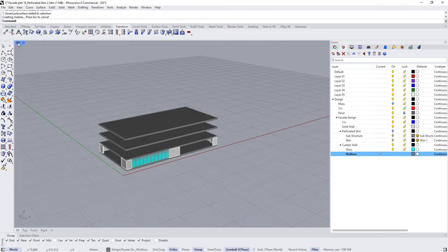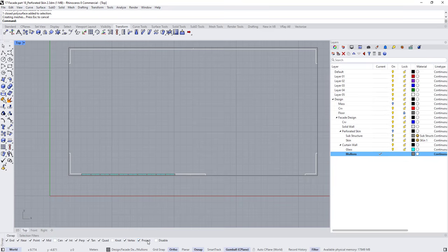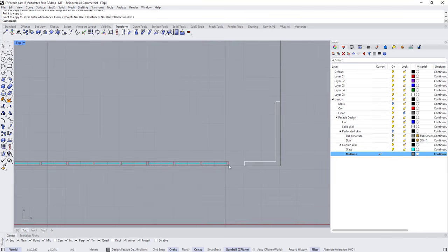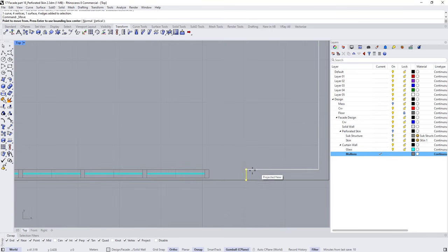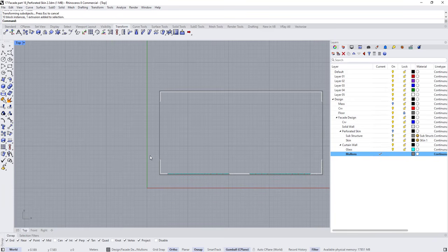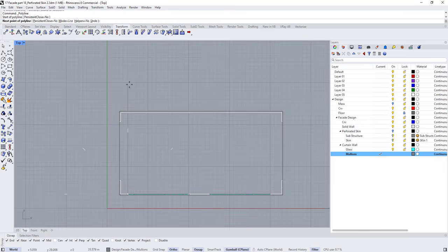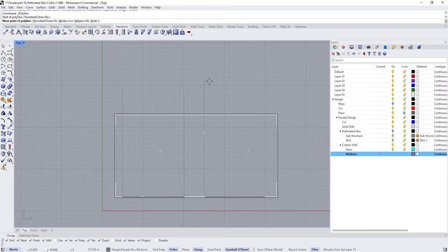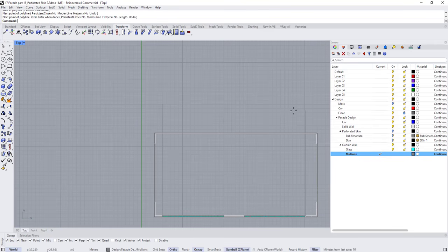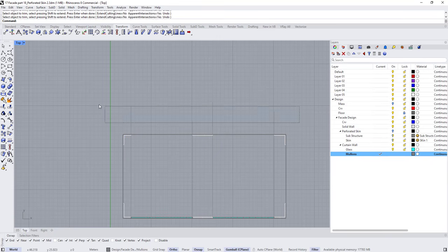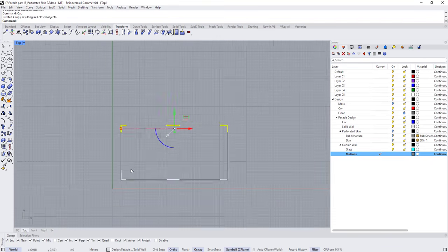Okay, so let's stay in the top view. Make sure to open the project. So I'm going to select all of this, a copy from here to here, right click, use the command, hold Control Shift and move this here. Now let's draw a line here, right click to bring the command again and draw another line here, right click to bring the command again, draw a line here, right click to bring the command again and draw a line here, type trim, select all of this, trim this one and this one. Now select all of this and type cap to close it.